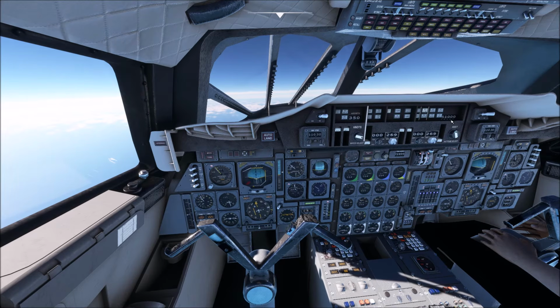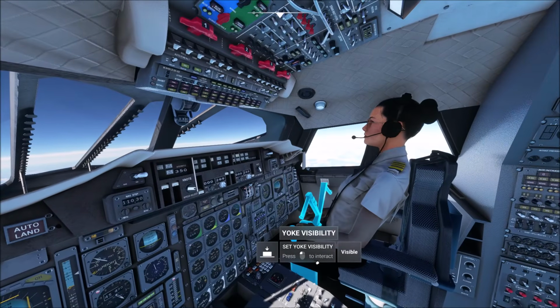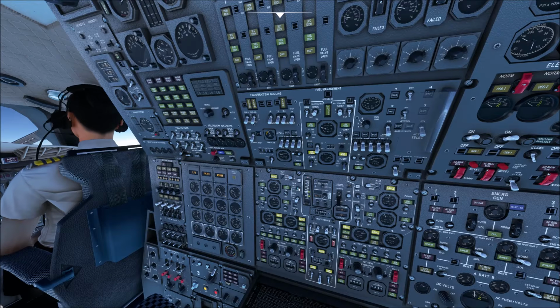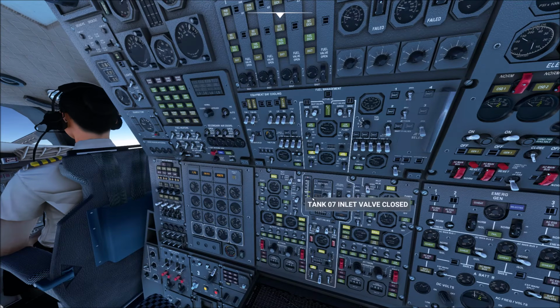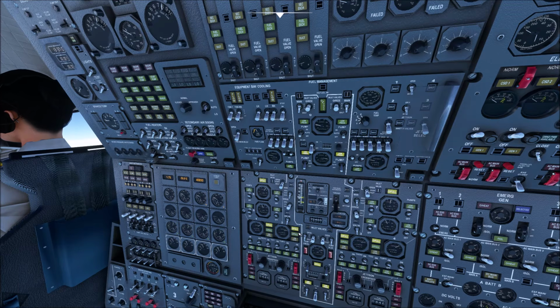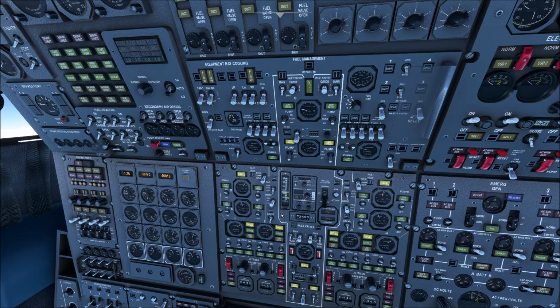Flight level 5-1, and the reason I picked that is that max cruise would engage above 50,000 feet. So I'll give it the extra 1,000. It doesn't have to be 1,000, it could be 500 feet if you wanted to. And that will move us up. Yeah, we're still gradually accelerating. The wobbling is usually due to turbulence outside the aeroplane. Head back and check on that fuel flow, because it looks like they filled up the tanks. Shut those now. Try and push that further back in a minute.